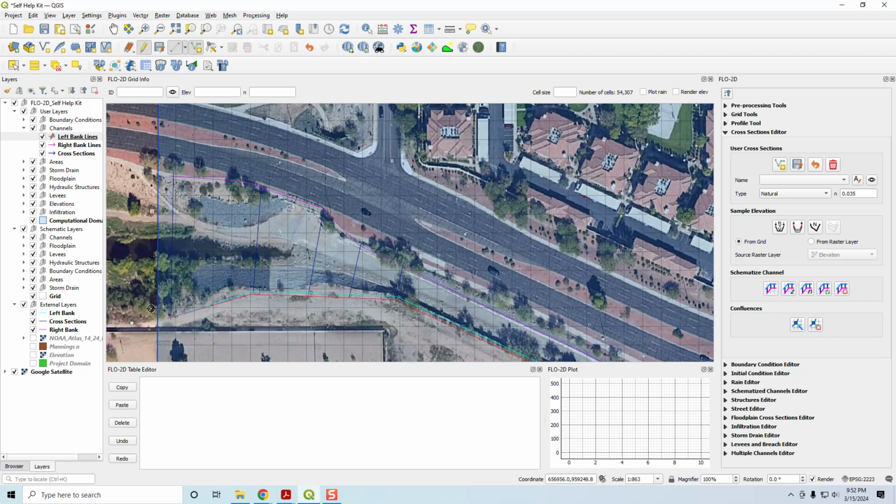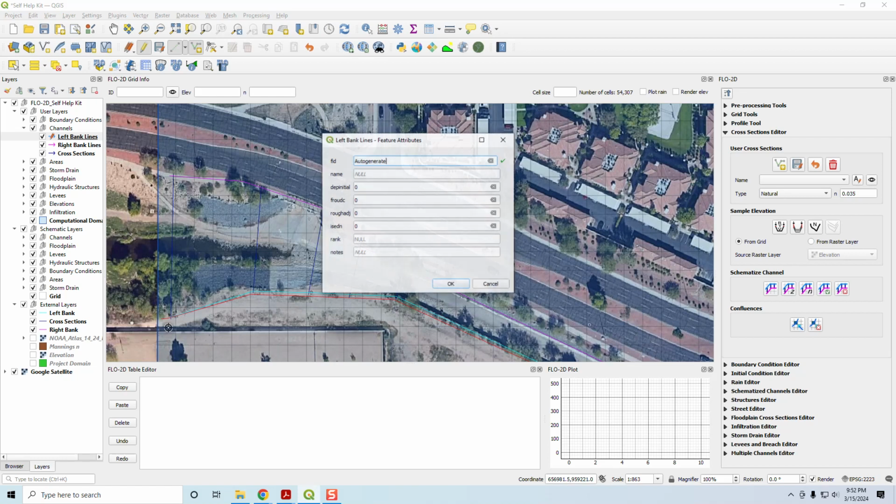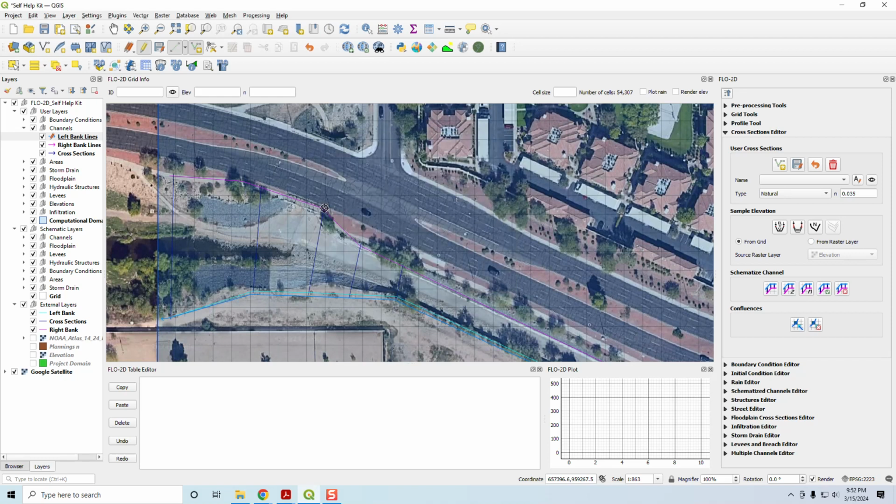And then the last one, this is our very last grid element. We want to run this channel all the way up to the boundary. And I'll right click and close that last line, 0.9, tab 0.2, enter. And that, the left banks are now done.